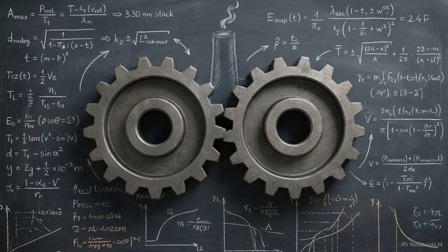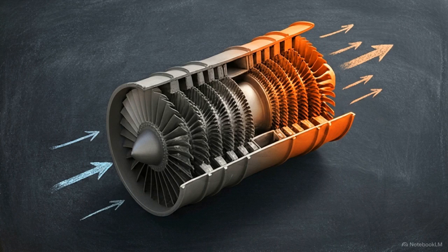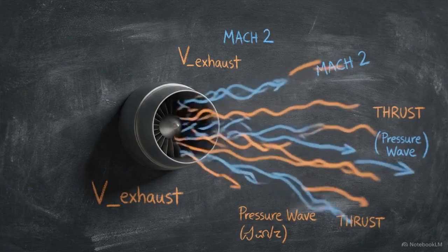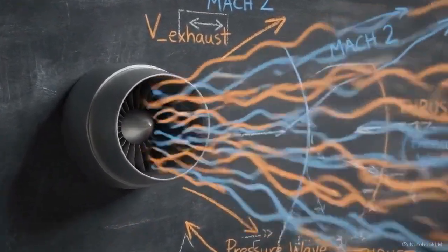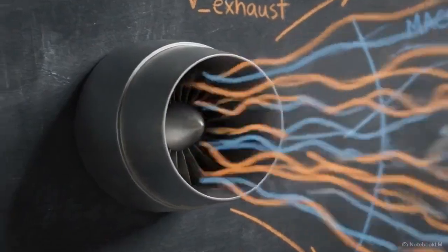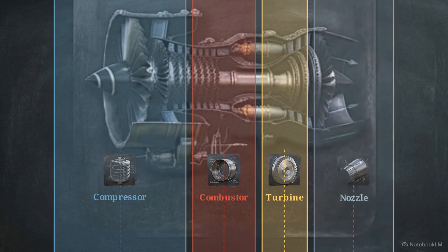These heavy, stationary modifications are the ultimate tools for extracting maximum rotational energy. They deliberately leave as little kinetic energy in the exhaust as possible, but in aviation, the engineering goal completely flips. You want to extract only enough rotational work to keep the compressor spinning, intentionally leaving maximum enthalpy in the gas. Instead of turning a heavy generator shaft, excess high-pressure gas is funneled through a converging nozzle, violently converting thermal energy into sheer kinetic energy.